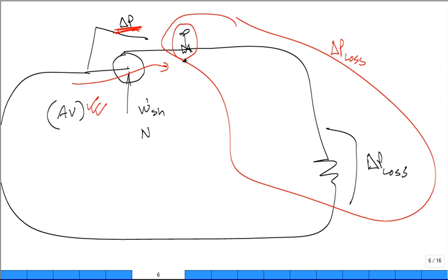This valve is now closed. You just turned a great pump into a big egg beater. That pump has a real high delta P. Is there any flow through the pump? And the pump's just going to heat up that water. Oh, it's going to sling that water around inside the pump.